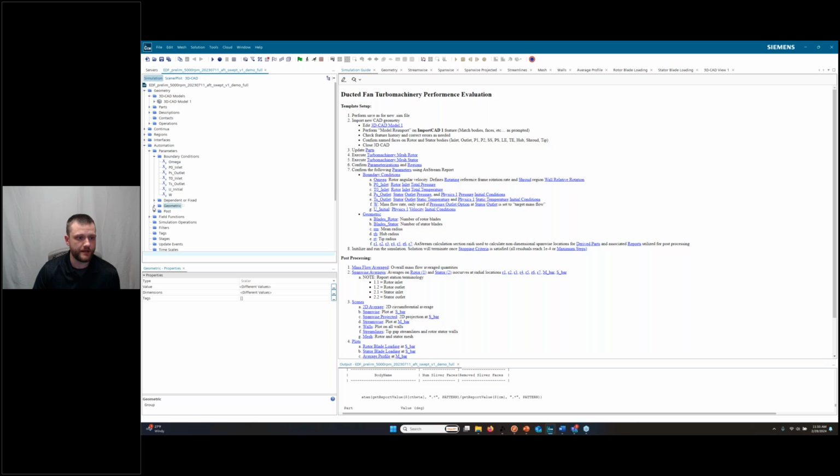I also have some geometric items in here where we can see I have these R values. And these R values are actually the same mean line radius values that were used in AxStream for the 2D mean line analysis. The reason I put those in there is that these will automatically calculate many of the same values, and then you can interrogate those against AxStream as needed to find out where we can improve things, or maybe we need to adjust some loss coefficients or something like that to drill down on our design. So once we put that information in and bring our geometry in, we're good.